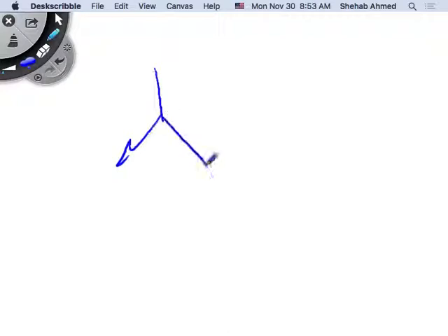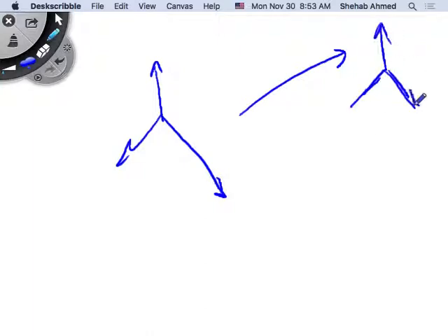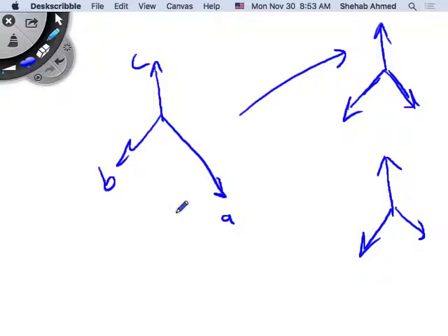This is an unbalanced source. I can chop it up into two balanced three-phase sources, but one, okay, so if this is A, B, and C, right? One will look exactly the same. It will have the same sequence, right? If you're standing here, these are phases. They're rotating with time, right? They're actually changing with time. This is a frequency. They have frequency content there. If you're standing here, you will see A first, then B, then C, right? And this is called the sequence of that voltage supply.